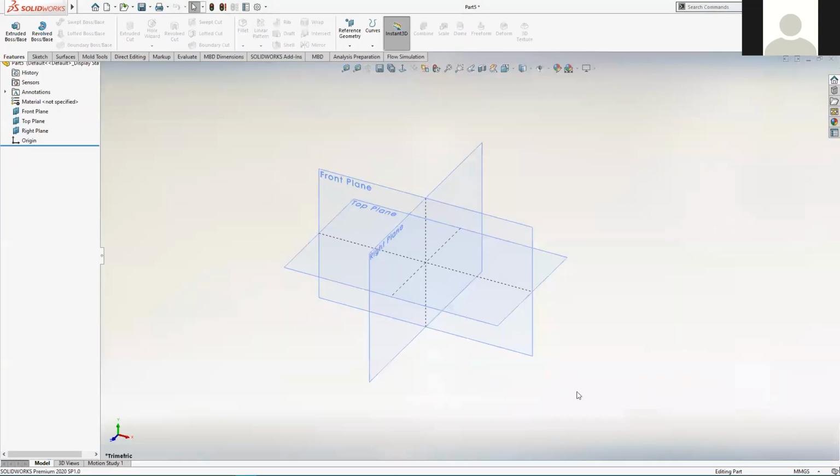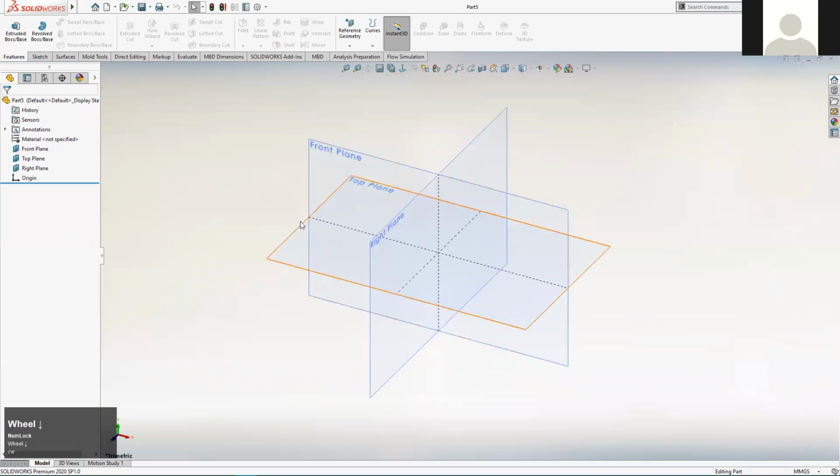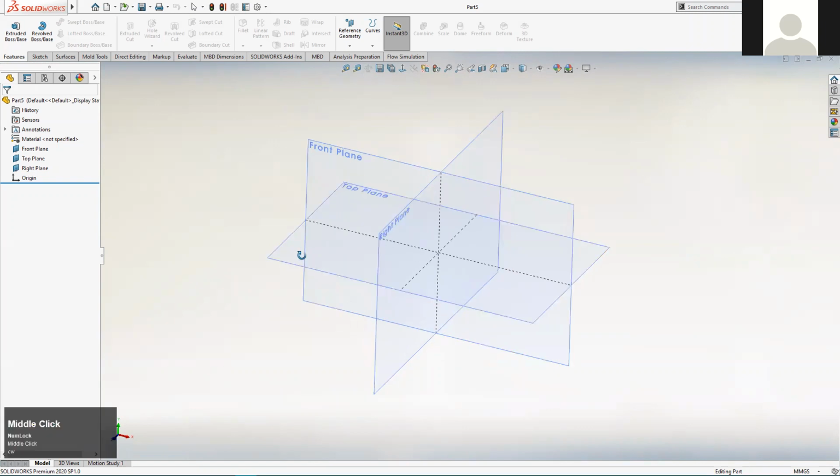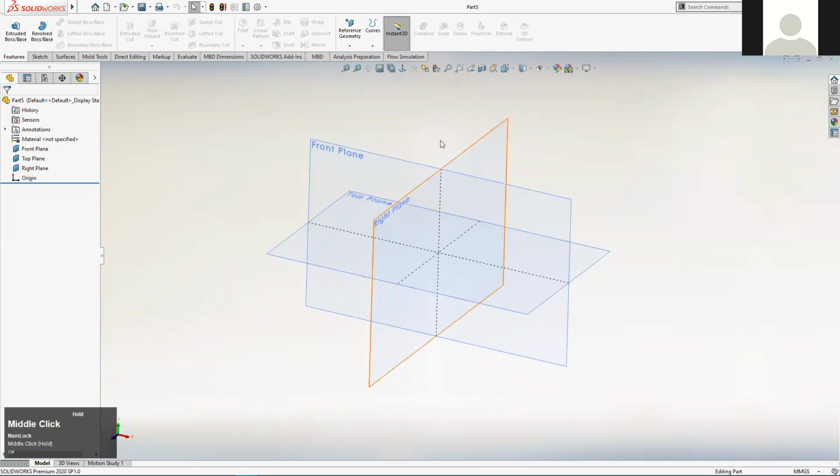You should then drop into the part modeling interface. We touched on this last week, but it's worth reiterating just before we get going. If you can't see the 3 base planes here, there's various reasons why that might be the case. The simplest one is to just try clicking on the eye icon at the top.